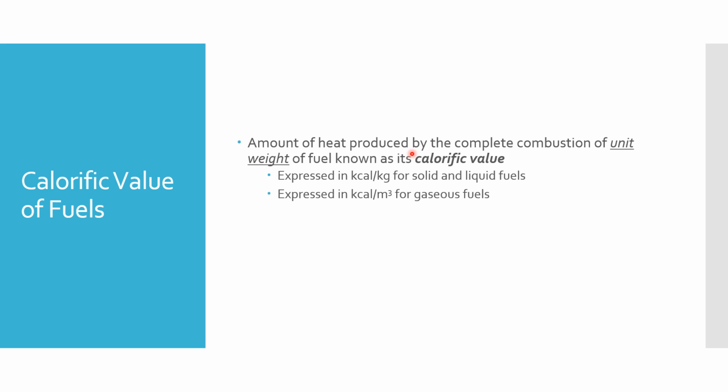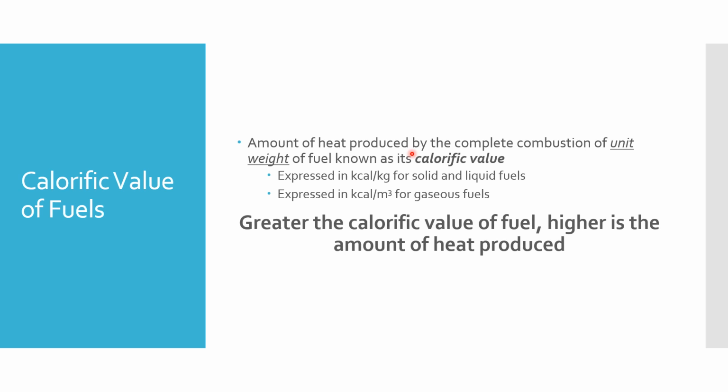So the calorific value is expressed, for example, for solid and liquid fuels, in kilocals per kg, and for gaseous fuels in kilocals per meter cube. So how many cubic meters of gas need to be burned to produce how many kilocals of heat energy. That is what this calorific value tells you. So the greater the calorific value of a fuel, the higher the amount of heat produced, and that fuel is considered to be of good quality. A fuel with low calorific value can also be combusted to produce electricity, but that will produce a lot of pollution, because it is a low quality fuel.